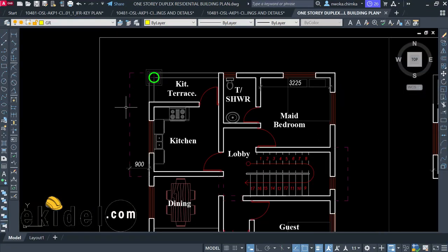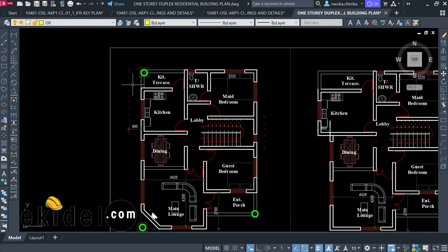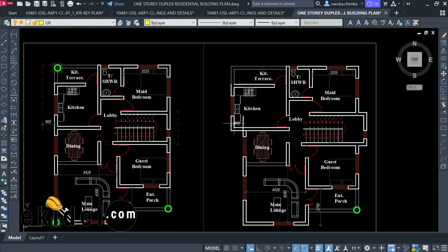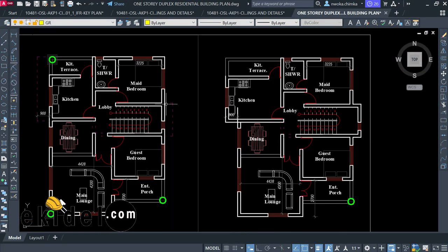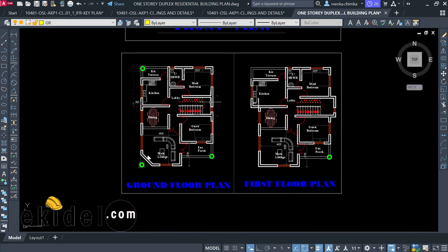Yes, cantilever slab there. And also it is here too. So once I see these two, I'll just refer to the first floor plan, and then you can see how the shape is also. So basically this is a cantilever, and also on this place too, here is a cantilever around the staircase. So now I have known that there is a cantilever slab on this building. That's the one thing I've seen again.